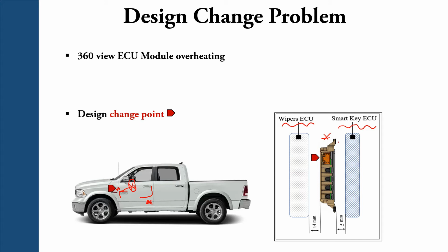But I'm just trying to lay out the mindset here: when you move from A to B, problems show up. How are you going to avoid problems? I can give you some hints right now. You want to think, can I move this module out of there and go somewhere better ventilated, and away from other heating elements, or do I have no choice? Secondly, how can I make the module passively dissipate the heat in a more efficient way? Those are the details you want to look at when you're talking about the change with the DRBFM mentality.